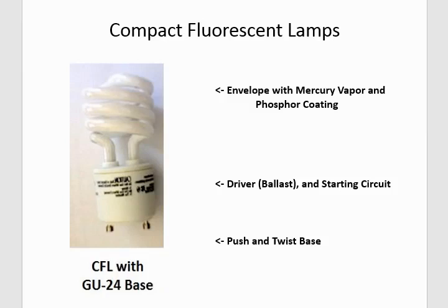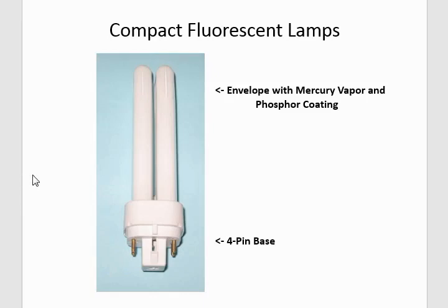Here's an official CFL that you can use non-residential and claim its wattage directly because it's got these GU24 push and twists on the base. Here's another official lamp. Residential, anything like this, during this code cycle, the 2016 code cycle, was considered high efficacy because it has pins. Okay? It has 4 pins, which means it has filaments in between those pins, which means it should be dimmable